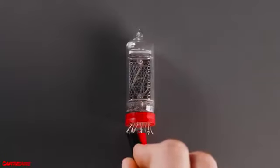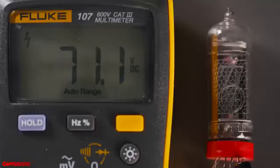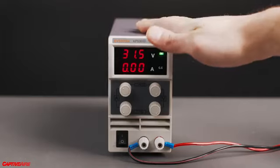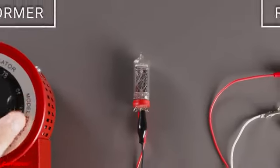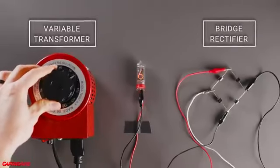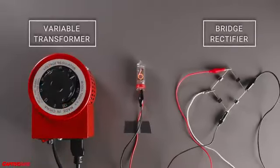Each one has a different pin at the bottom. Unfortunately, these take a lot of voltage, like 85 volts DC just to turn on. My DC power supply doesn't even go that high, so I use this variable transformer and the bridge rectifier we made in the last video to get higher voltage DC. If you haven't seen that video, I've attached the link in the description.